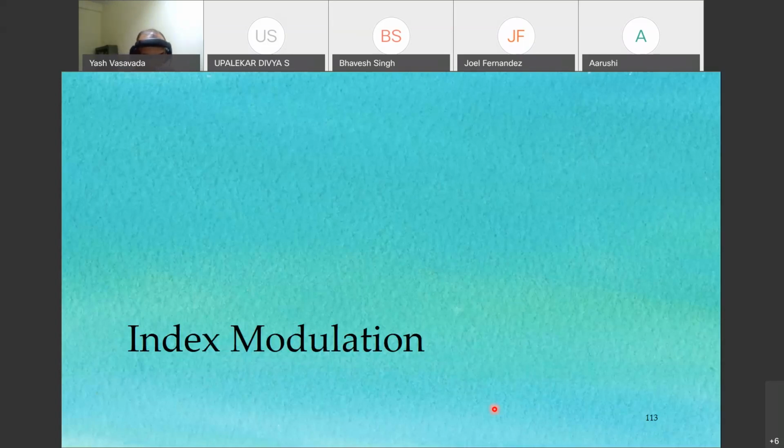And then we were essentially transmitting that symbol, and then we were letting the receiver figure out which of these multiple symbols has been selected. And so in context of 8PSK, if the receiver figures out that, okay, symbol number 4 has been selected by the transmitter, that act of figuring it out gives the receiver 3 bits of information.